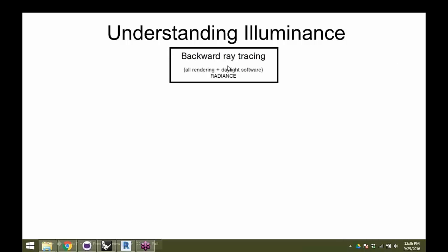and really all of them. I mean, some of them we're already kind of familiar with. Like a lot of you are already familiar with solar radiation or the energy of the sun that is coming and hitting surfaces. But both illuminance and radiation, all these things are calculated by the same computational method, which is just called backwards ray tracing. Which, I mean, we'll get into a little bit more detail about what that means later, but really all these metrics that have to do with the solar intensity and the intensity of light, they're all using this basic principle, which is the same underlying principle of all rendering engines, and of all radiation and illuminance values.